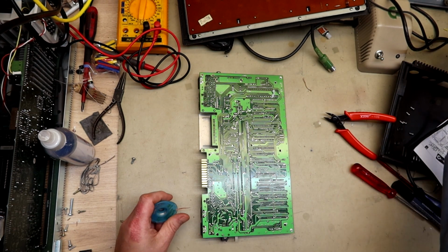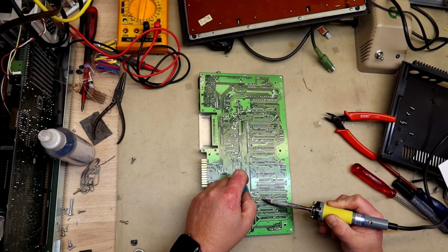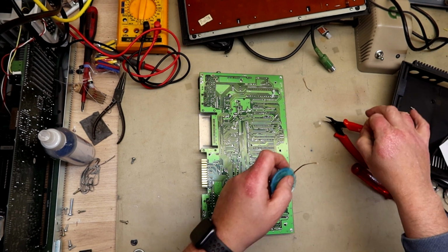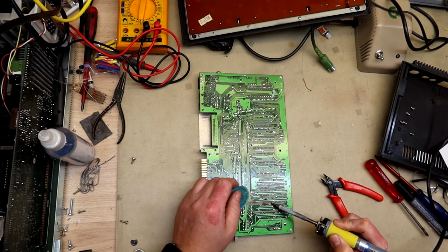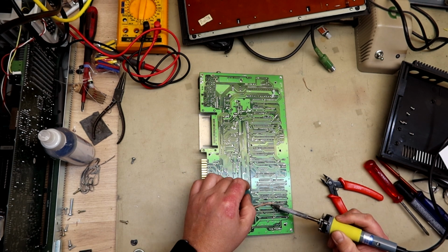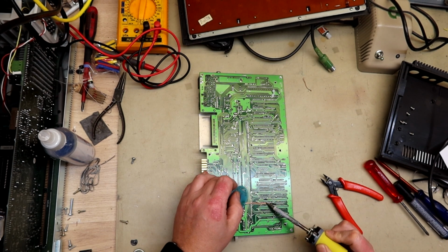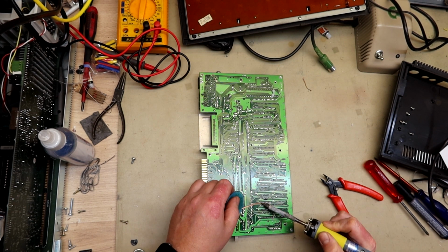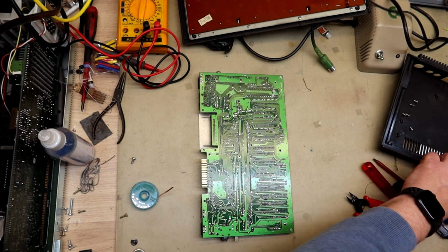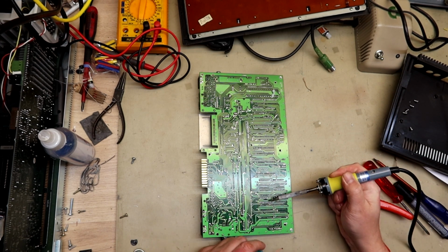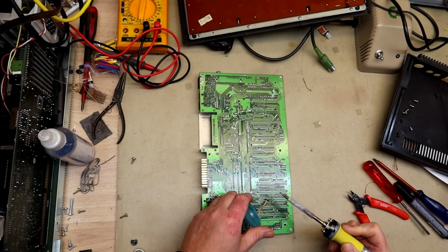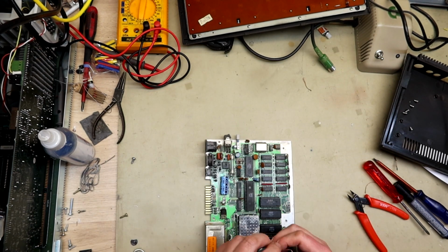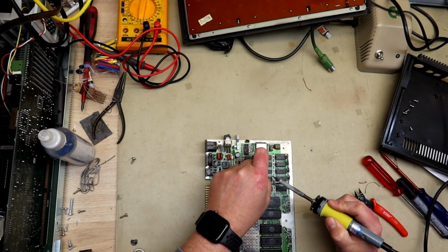The most important thing to remember when you use desoldering wick, besides using a kind with a good amount of flux or rosin in it, is to keep the stubs so short that you don't have to use too much heat. And you can't overheat each pad either, so move it to the next pad if you can't suck up more. And as you will see, I also use a trick where I do desoldering from both sides on these boards where you have true plated holes for the components.